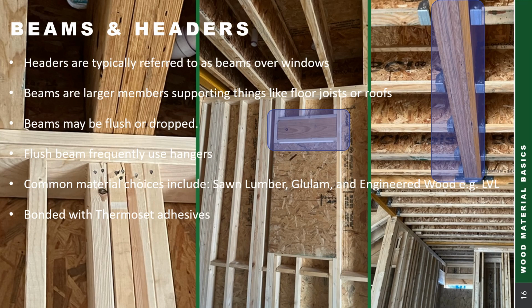Some of the common materials that are used in beams and headers would be sawn lumber, which is shown right here, or we could have a glulam or a laminated veneer lumber, and this is an example of a laminated veneer lumber. One thing to keep in mind with all these materials is they are bonded with thermoset adhesives. So if you are wondering what's going to happen if there was a fire or if they get wet, there should not be a concern with the resins debonding these materials which have been glued together.